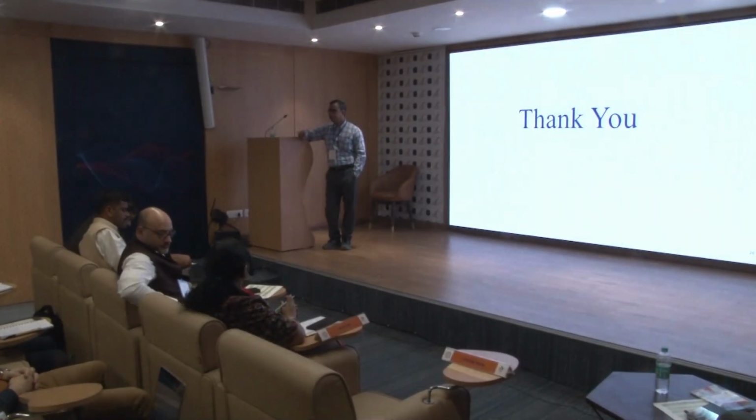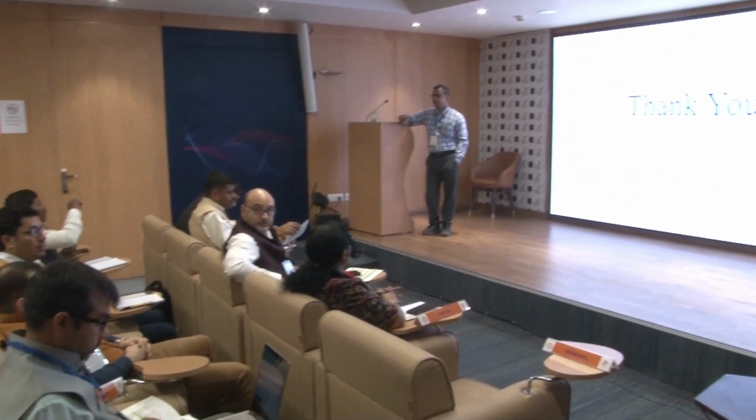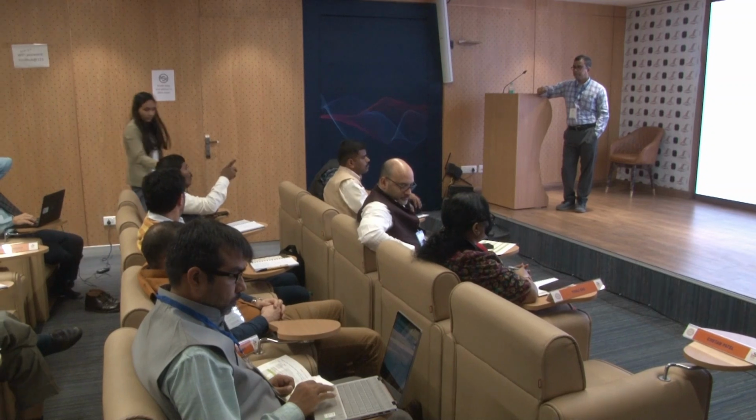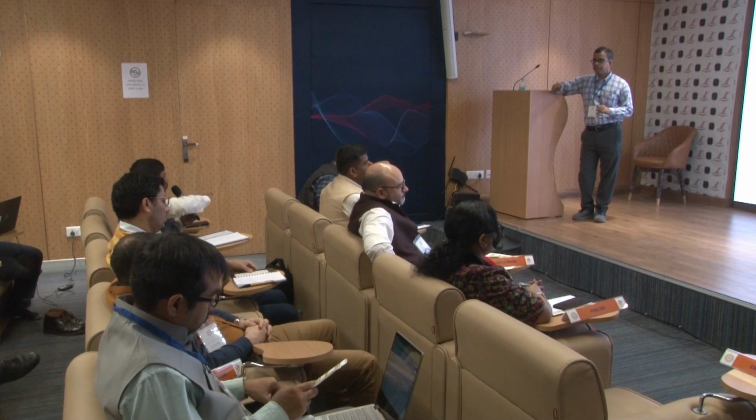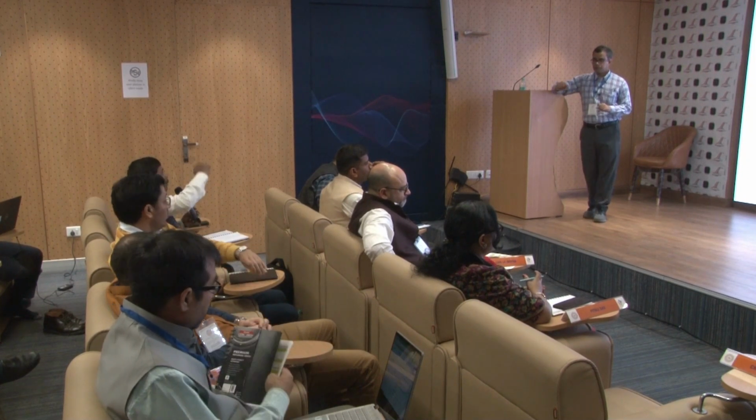I have a question, and a very nice presentation. You said you reduced the valve seating velocity from 1.28 to 0.38 meters per second, and I think you are sending air in the bottom also. So this may lead to a repercussion, that is, the valve can move up also because of this.